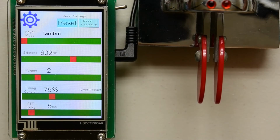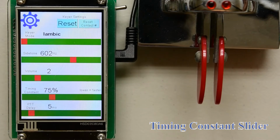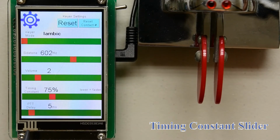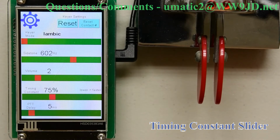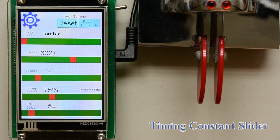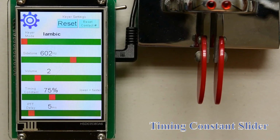The push-to-talk delay slider won't be useful to everybody, but if you need some sort of a push-to-talk contact before you make your key contact, then you can set a delay of anywhere from 0 to 50 milliseconds. And if that's not enough, you could always get into the Arduino sketch and make the change that you need to on that, so that your equipment will be ready for when you make key contact.